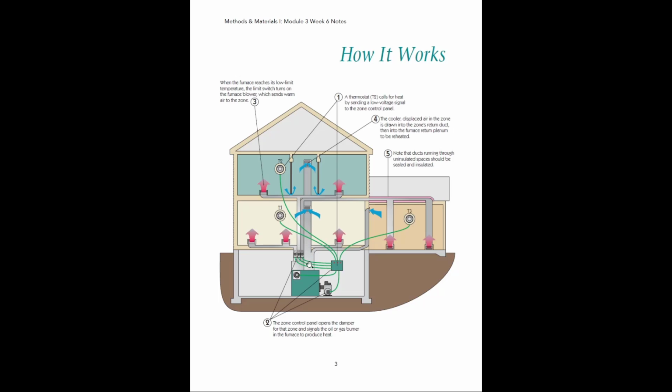And then if you look here, we have a separate duct system, and this is our return duct system, okay? So what's happening here is all of the air that has been distributed through the supply ducts within the building is then being pulled into the return duct system.